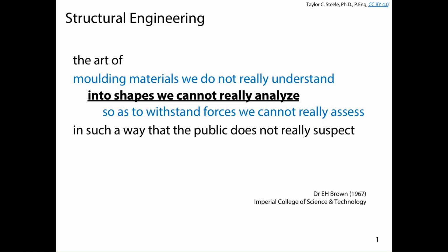So far in this class, we've been talking about some components of this more interesting definition of structural engineering. And last day, we talked a little bit about how we can put some of the shapes that we talked about on Friday last week together to make a structural system that's capable of supporting gravity loads on the floors. Concepts of tributary width for joists, tributary area for girders and columns, and we had time to do a brief example on how we got the loads on the joists and the loads on the girders.